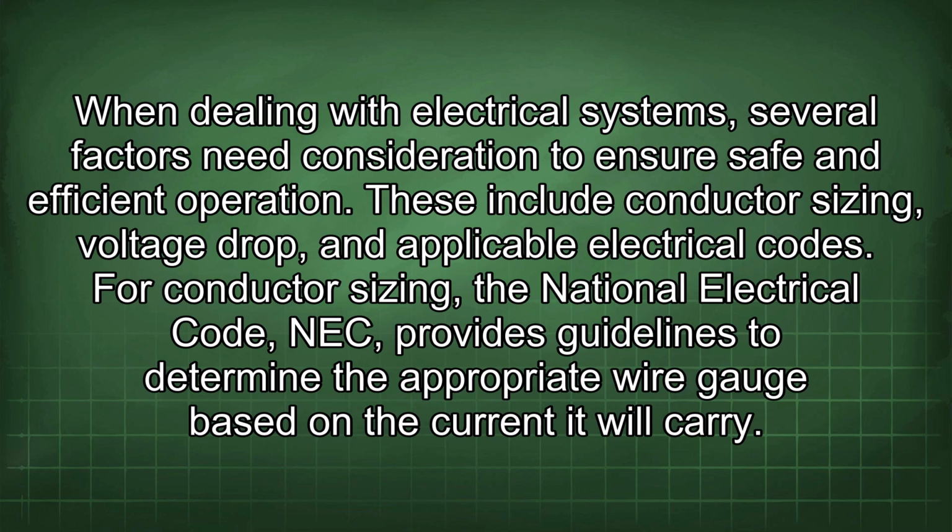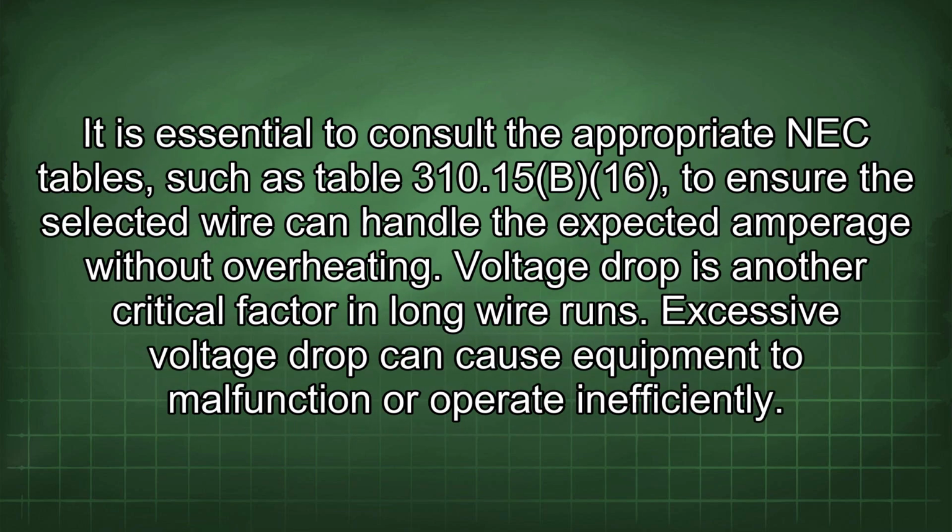For conductor sizing, the National Electrical Code (NEC) provides guidelines to determine the appropriate wire gauge based on the current it will carry. It is essential to consult the appropriate NEC tables, such as Table 310.15(B)(16), to ensure the selected wire can handle the expected amperage without overheating.